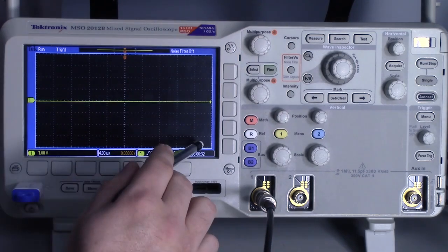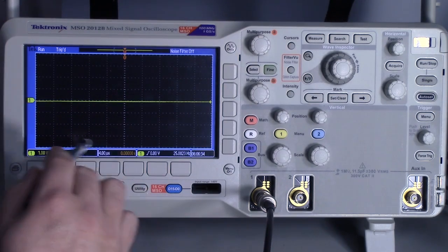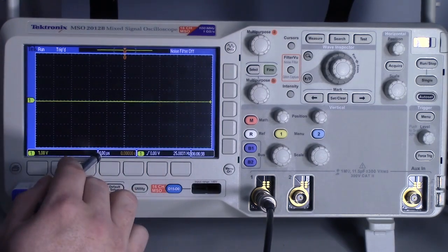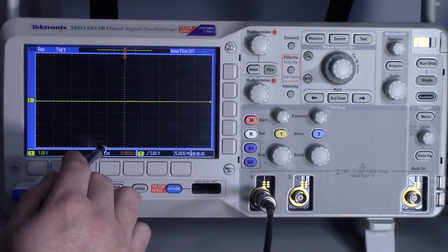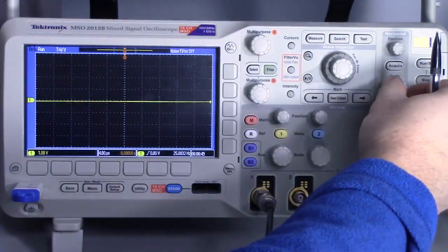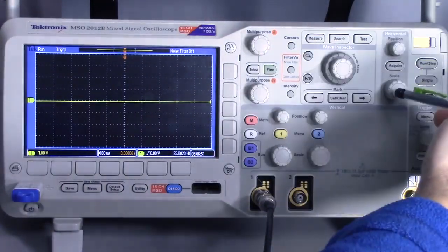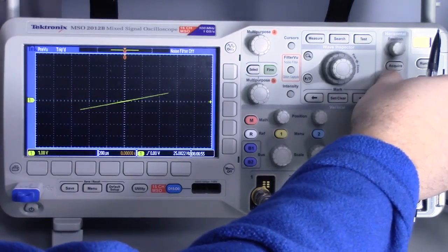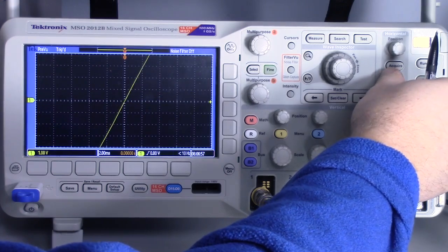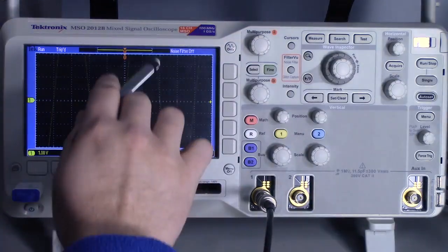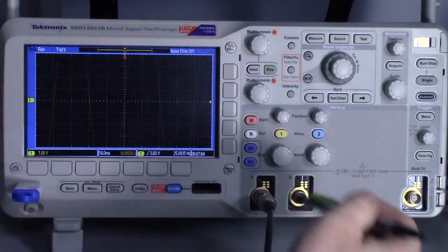So the horizontal scale is 4 microseconds. So if I've got 10 divisions, it means from this side to that side is only 40 microseconds. So I have a 25 hertz signal going in, so this is far too small. In order to adjust the horizontal scale, I'll go over to the horizontal section of the oscilloscope, and we'll increase the amount of time. You can see we're actually starting to see some slope. Now I can see most of the sine wave.